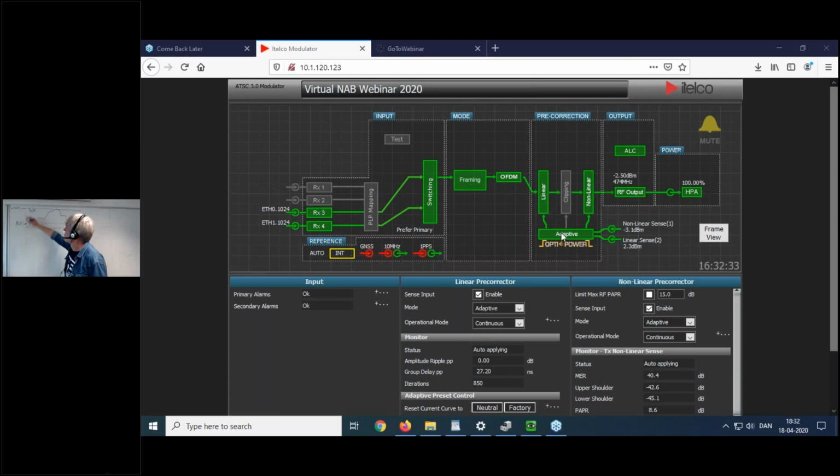When we do that, we bring the RMS closer to the performance of the amplifier determined by the power supply. Now I will just draw it the other way around. Say we want to reduce our crest factor to around 6 dB. But that means we cannot reproduce the peak.